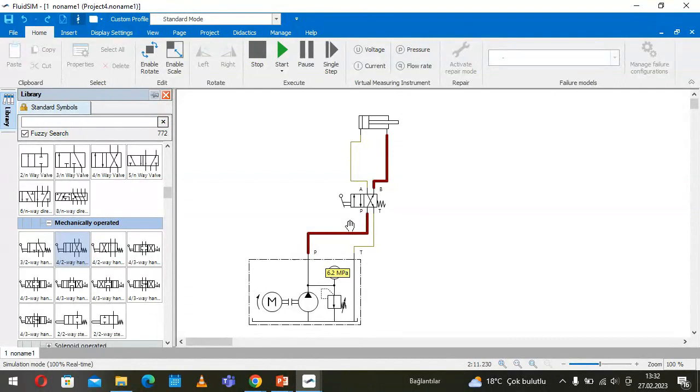This speed is mainly related to the exhausting of the air inside of the piston, and therefore we have 2 exhausts, one for each position of the valve, so that we can very quickly exhaust the air from the piston, so that the piston moves more quickly. Okay.